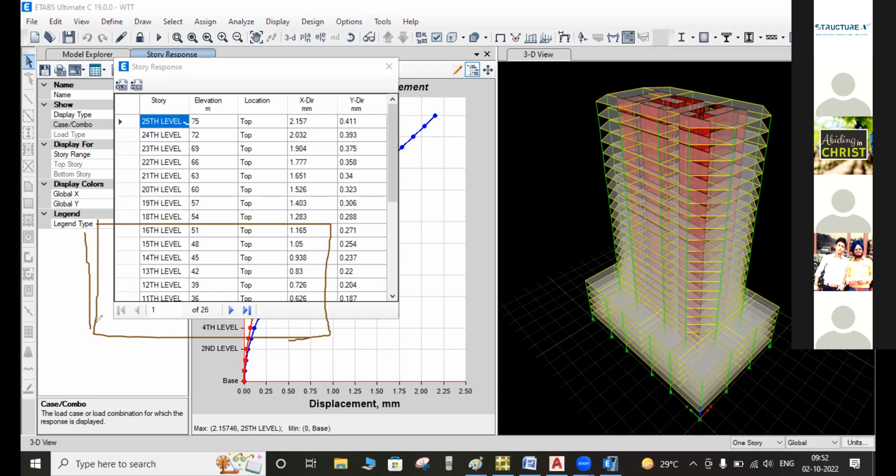The control deflection we have to consider is the span. I am asking whether our result is satisfactory or not. Sir, basically we export to SAFE to perform the short-term deflection and long-term deflection checks. Basically we identify the deflection in the slab. These are the deflection portions shown in the members. We apply different checks on the behalf of control, whether our allowable deflection is okay or not. We will check these in SAFE.